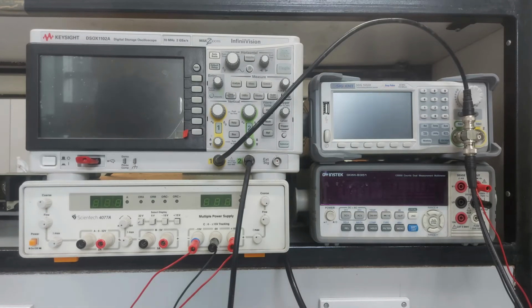So that is why one parameter is defined, that is the slew rate, which tells us how much maximum change in input signal we can provide. I mean, how much frequency of the input signal we can give so that the output is not distorted and the op-amp can respond to that fast or high input signal. Usually it is known as volt per microsecond. For the 741 op-amp it is 0.5 volt per microsecond. So these are the things.